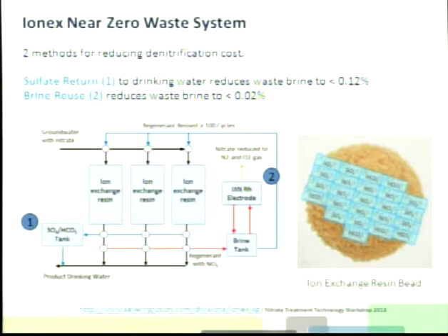So that waste, which is the concentrate salt plus the nitrate, is something that we will take to an internal tank on our system, and that will work through an electrocatalytic cell, and we reduce the nitrate, NO3, in that solution to nitrogen and oxygen gas. That permits the reuse of the brine for further regenerations and eliminates that one-shot use of the brine going to the truck and the disposal site.